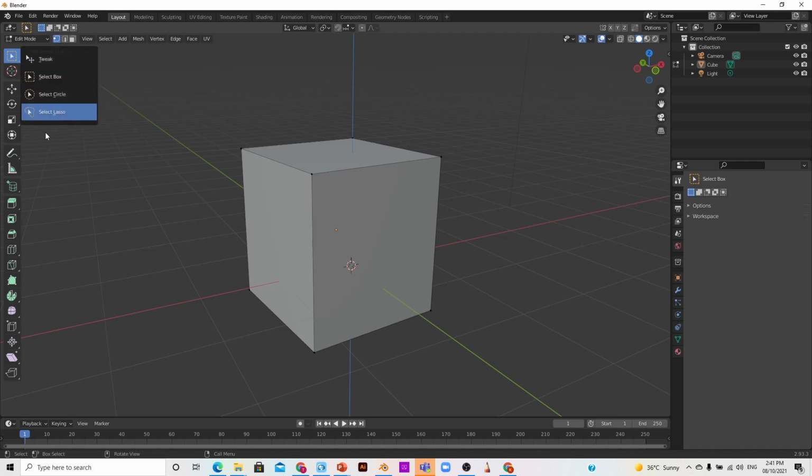these selection tools in the layout panel, because in the layout panel it's the whole object, but now in the edit mode you need to select the side or the corner or the edge. Okay, so let's try the other selection tools also. How to activate the other selection tools: move your cursor to the selection tool, and then press and hold the left key of your mouse, then you can activate it.